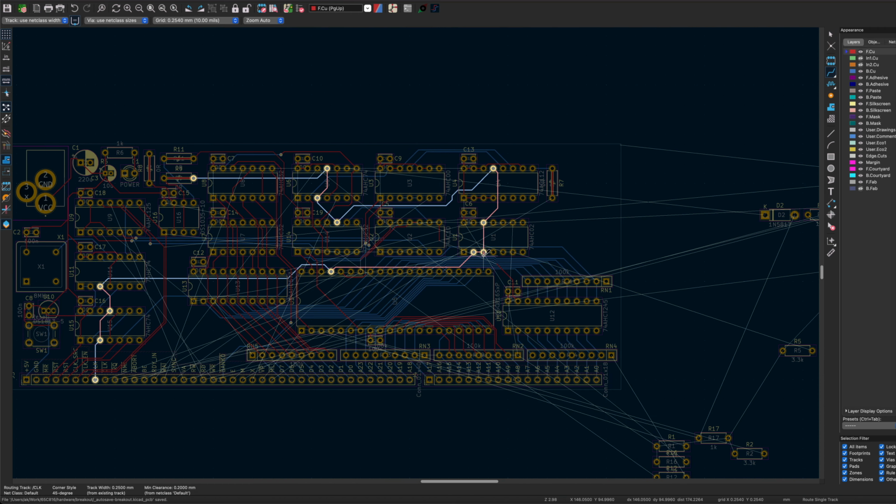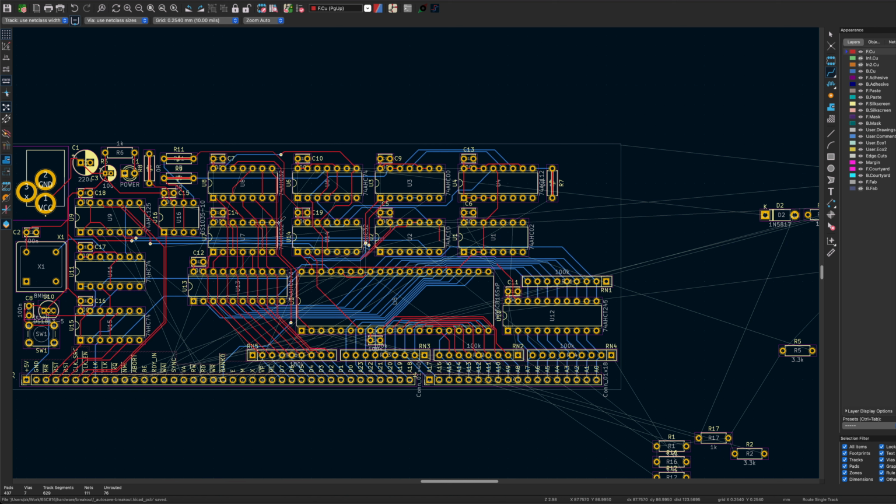So this is the final clock signal. I was able to route it in a continuous shape, not in a star shape, which is better. However, that makes it quite long, and we're probably going to have to make use of that termination resistor. I've also finished adding all of the ICs, and so now it's just finishing to route all the signals and making progress one signal at a time, I guess. Let's get back to it.